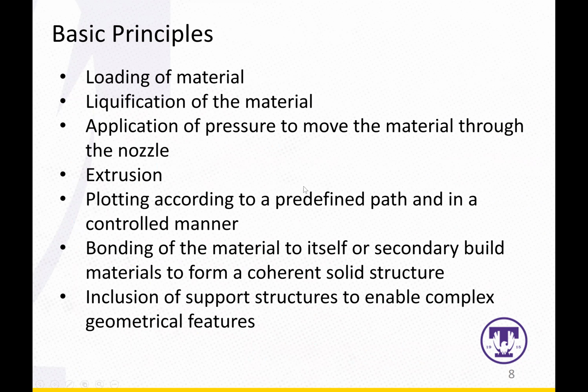As I mentioned, the second step will be the liquefaction of the material. Once the material is loaded, it has to be melted, right? And then the third step is to press the material through the nozzle such that it can be extruded onto the base.